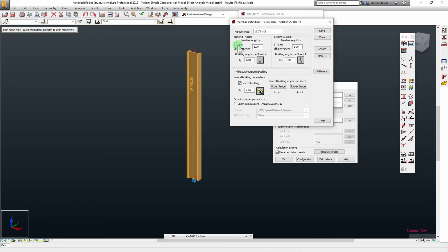This is buckling. We'll talk about this type of buckling. What we're talking about is our flexural buckling for columns. Okay, so there are various limit states depending on the section that you're using. For a column, it can fail by yielding, it can fail by flexural buckling, torsional buckling, or torsional flexural buckling, or even limit states related to the slenderness of its cross section, which are local buckling states for the member themselves. So all these different states can control your structure.